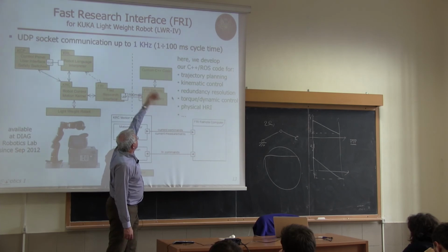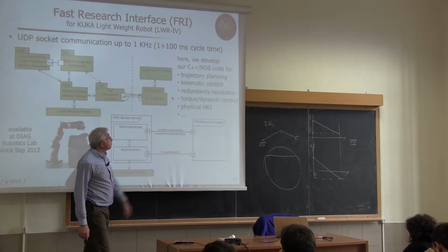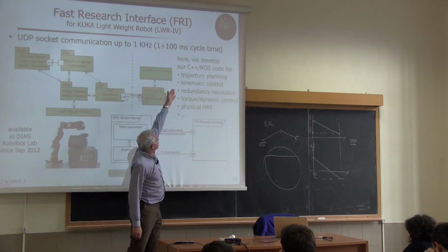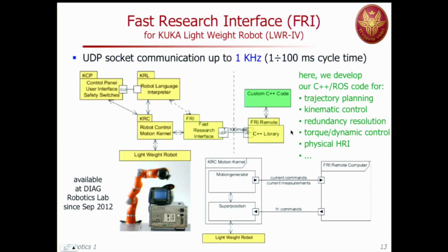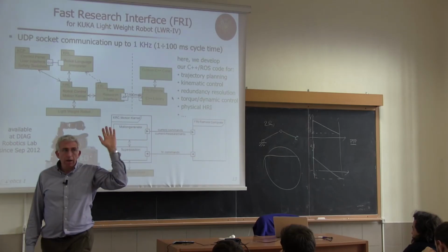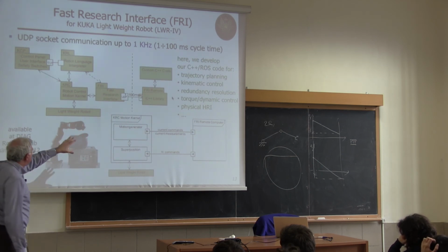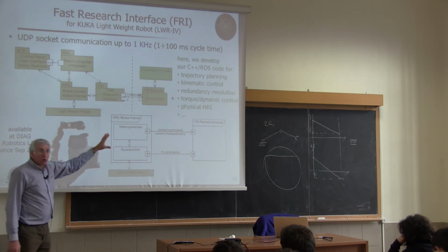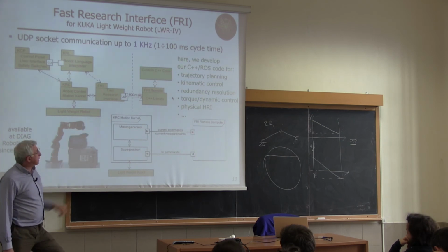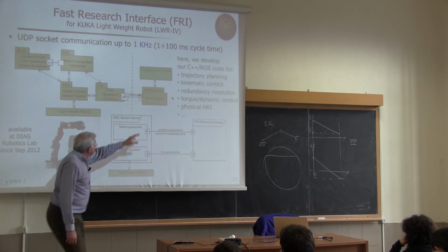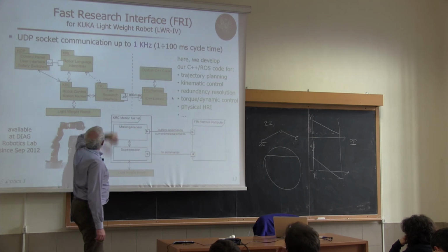outside, you develop your custom code. And we developed codes for doing kinematic control, trajectory planning, resolution of redundancy, dynamic modeling, torque dynamic computation, physical human-robot interaction with contact with the human. A lot of things that we do for research. Okay, so we developed our program there. We have libraries. We have ROS nodes developed in that area. And it interfaces with their